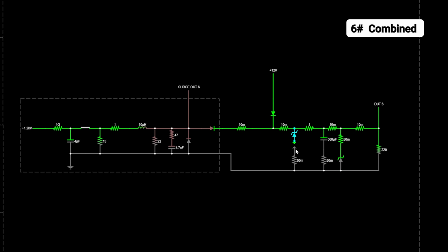Once it starts conducting, it takes the brunt of the power, making it so your TVS doesn't get destroyed. If we increase the size of this series resistor, it essentially will make the discharge tube take more of that power and the TVS diode take less. By adding an inductor, you also have the effect of making the discharge tube take more of that power.